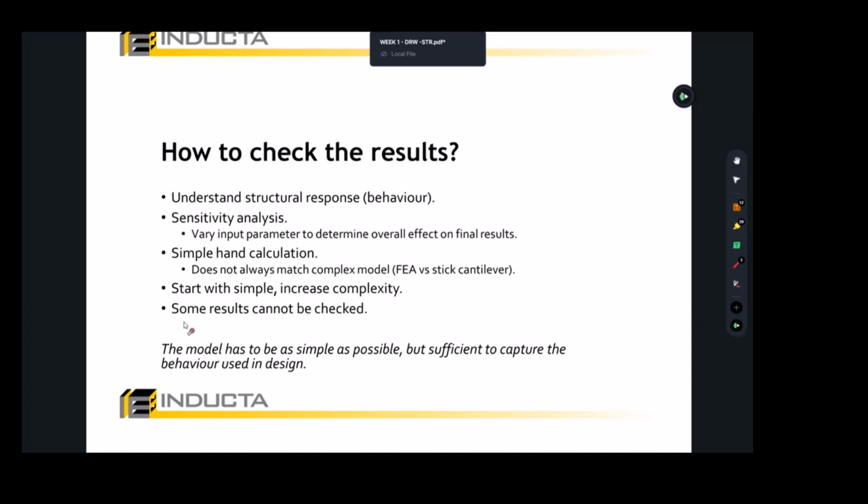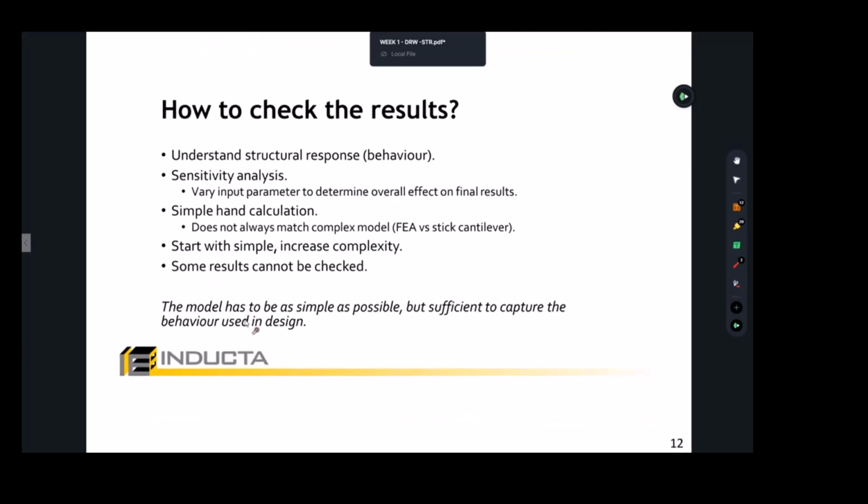If there is a special feature or special arrangement, you don't want it to take any load, and you don't know how to simulate it, then just don't put it in the model. When you detail it on your drawings, just let it be supported on the building. Don't let that element support the building. In other words, consider it as a non-structural member. Okay.